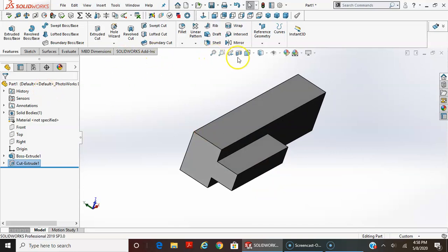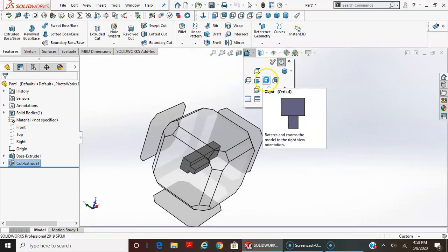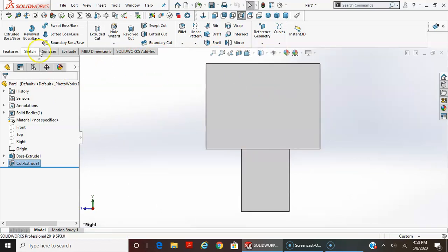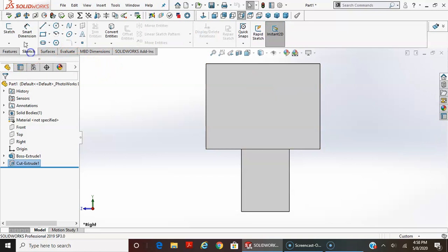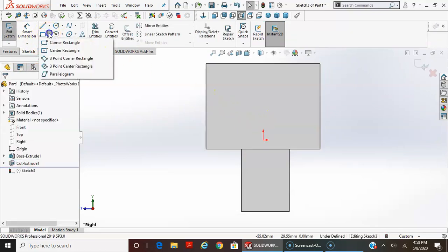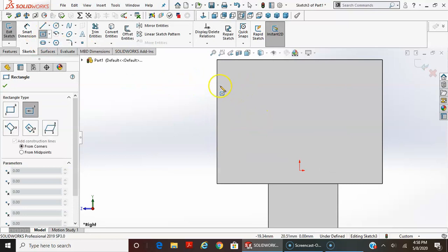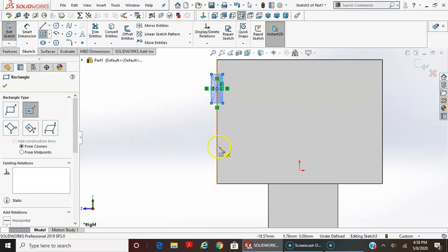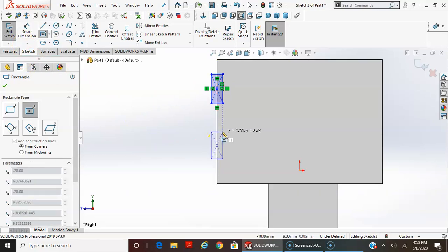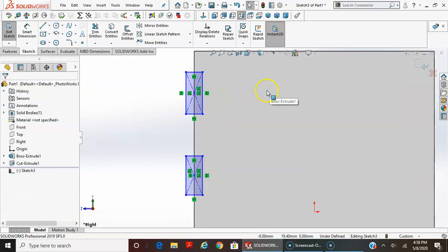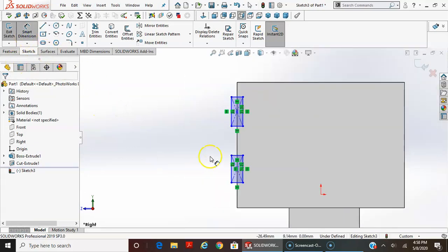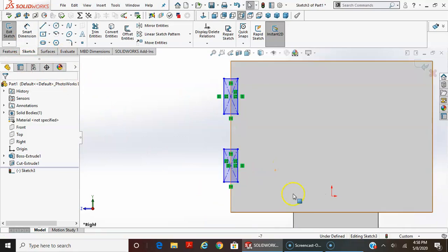and that is if I go to the right side view, there are rectangles here, and there's slots here, and I'm going to put one here like this. I'm going to put another one here. The center is equal. The depth of these is, well, I can't dimension accurately because I'm in metric, but the depth from this edge here to the bottom of the slot is 19 thousandths.